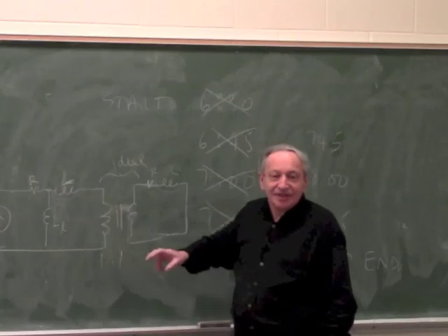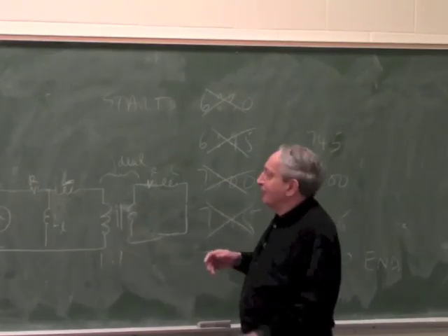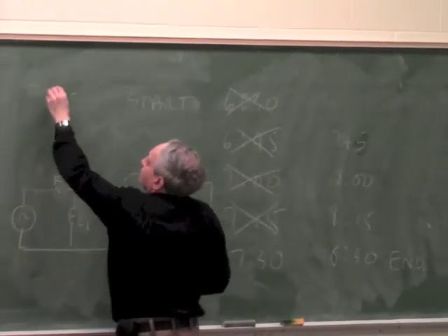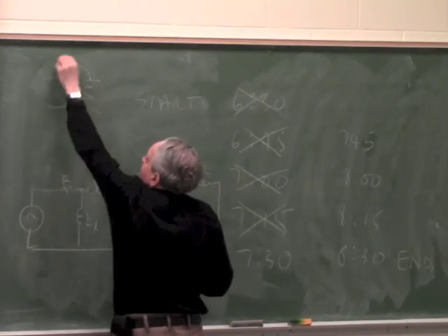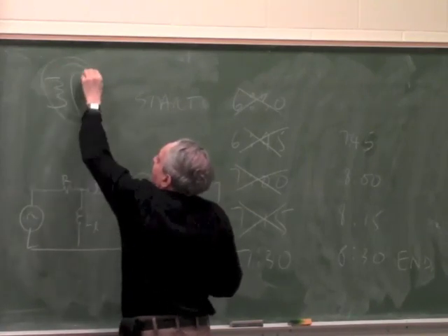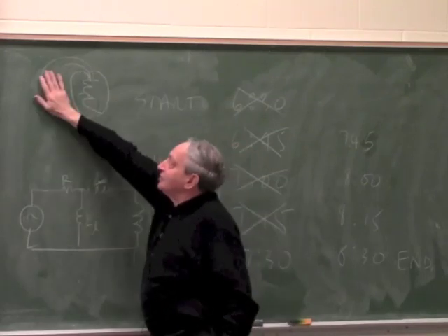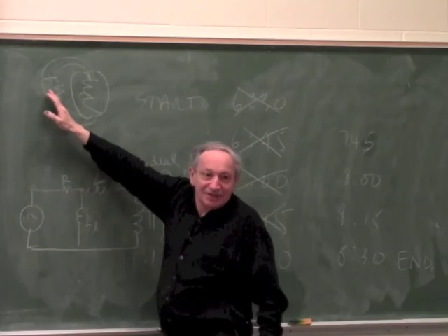So the inductance is a parasitic effect in the transformer, which comes from flux which doesn't engage both coils. If you have physically a transformer with two coils, you want all this flux to engage the other coil, but some flux goes without engaging the other coil. So this part of the flux just looks like an inductor. The flux which couples both doesn't have inductance.